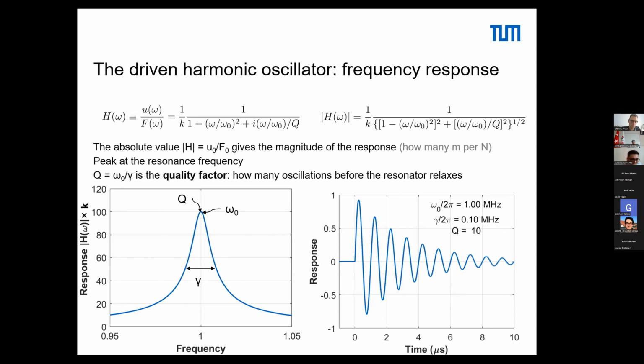However, when you make your resonator smaller and smaller, for example, the nanomechanical devices I've shown you, these have a lot more surfaces, and in these surfaces, there are always defects. Those defects are then going to play a more important role, and the trend is therefore that the quality factor decreases when you make your devices smaller. So that is definitely something that we see. However, this is really the quality factor, because when you make your devices smaller, they typically tend to vibrate faster. So your omega 0 is going to be higher as well.